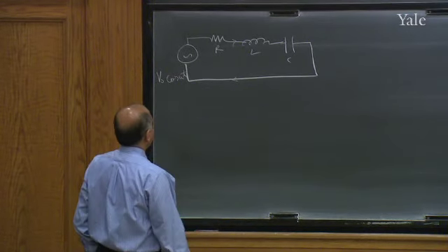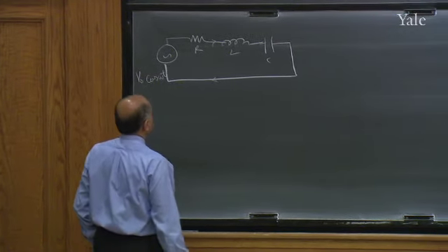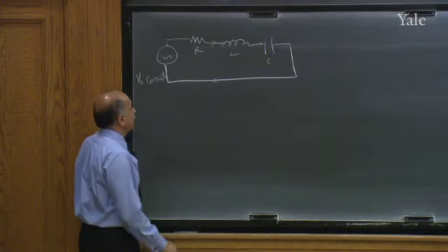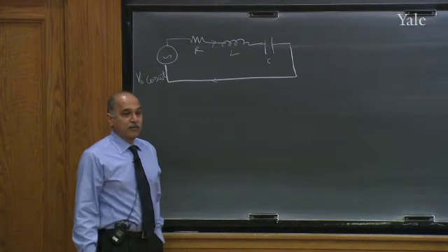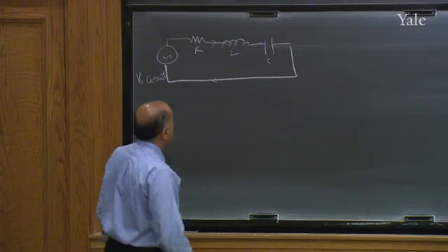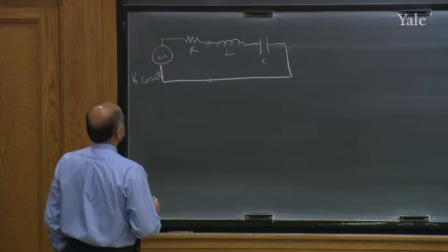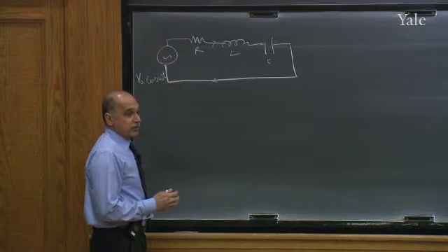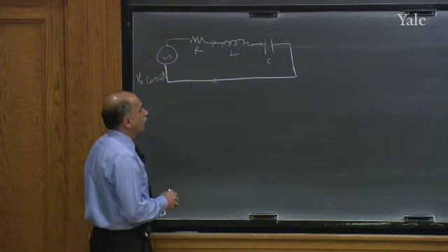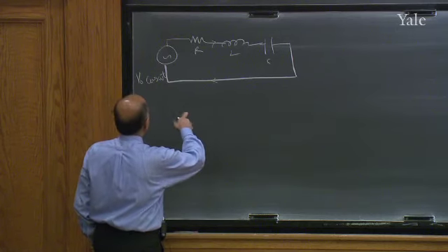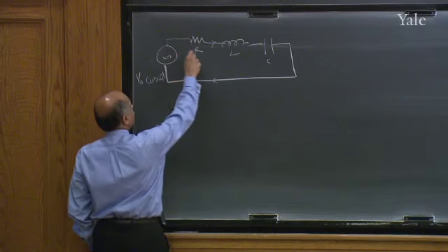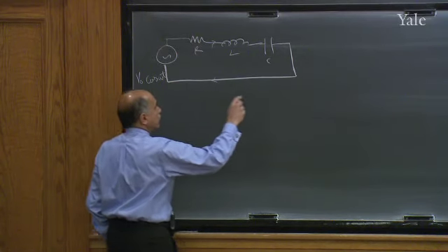Now, what makes it difficult is that unlike DC circuits, where you take the voltage and divide by some effective resistance, the equations here are not algebraic equations, but differential equations. So we'll write it down, then I'll tell you how we handle it. So for this circuit, you begin as usual, you go around the whole loop, and you add everything to 0.